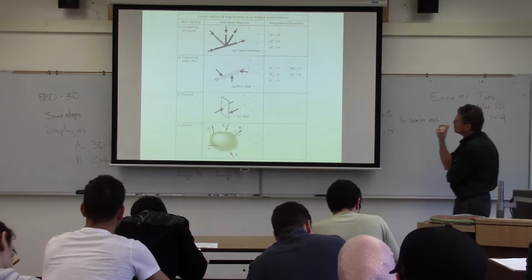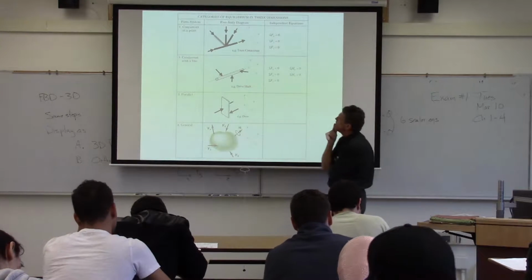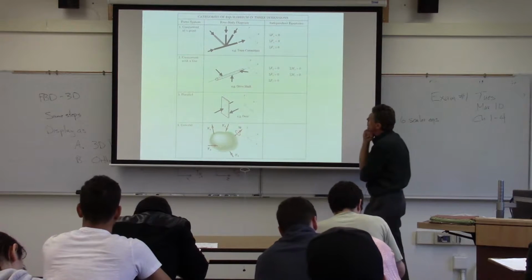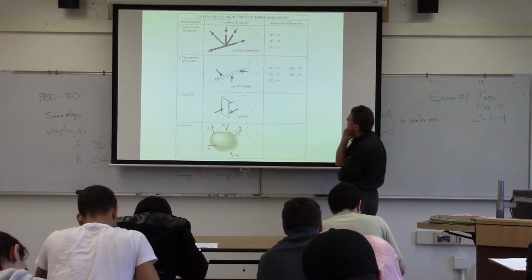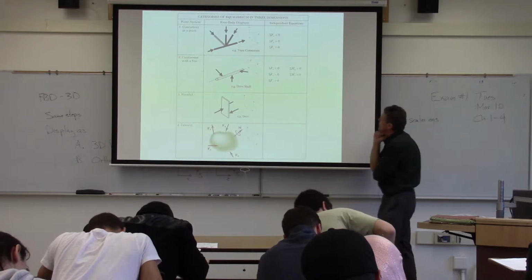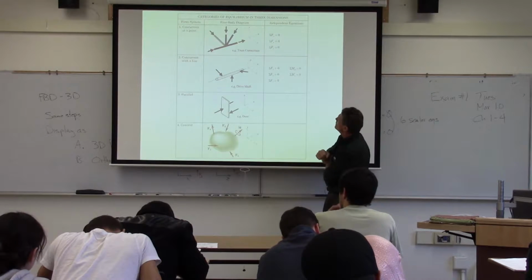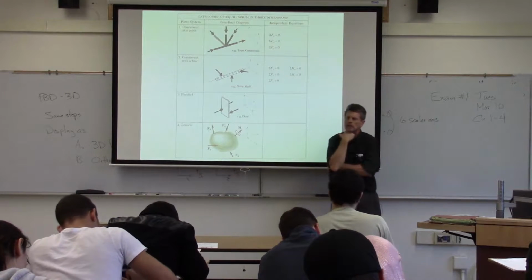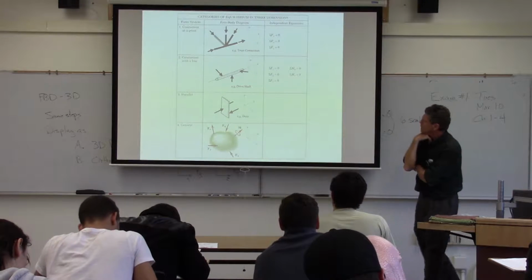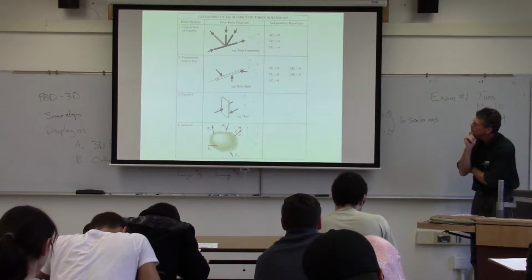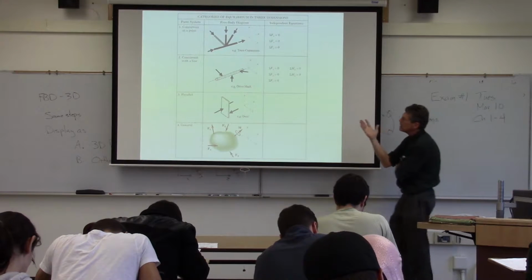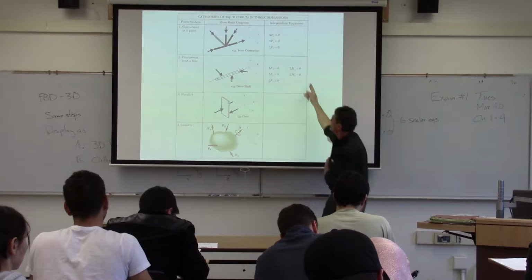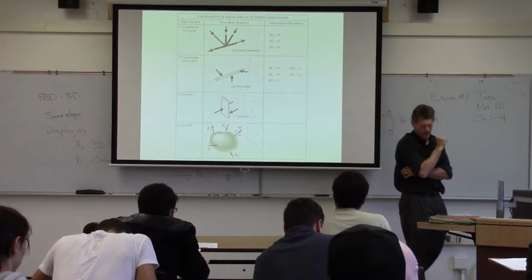Next one's a rather unique one to 3D: if they're concurrent on a line. So like a drive shaft, and you've got a set of brackets that are tied to it and that sort of thing. Well, what we'll find is that we can resist Fx, Fy, and Fz. We can also create couples because those will be out of line along the y direction and along the z direction, but we don't have anything resisting that x direction, which is kind of good on a car because we actually want it to rotate. But again, if we end up with a set of forces that are all going to a single line, then we're only going to be able to solve for 5 unknowns.